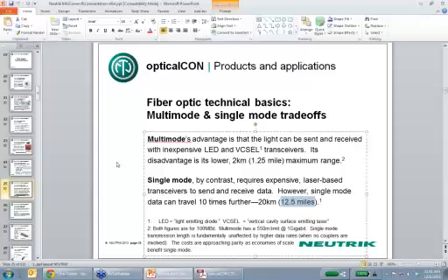It's a drag that with multimode and single mode cabling, we have these two different standards. You cannot tell other than by reading the cable jacket and from some sort of subtle color coding which is which. But this is the situation we live under. In the system integrator world, we typically have used a lot more multimode than single mode because it's been less expensive and because we've not needed those long ranges. That is changing a little bit over time.